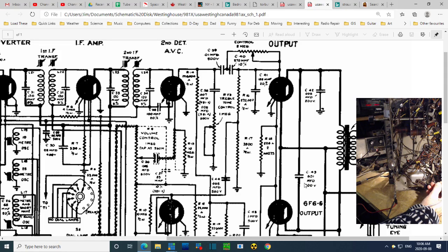That shouldn't make any real difference here unless it's huge, because you'd have to have a huge current flowing in the winding of the output transformer to cause a significant voltage drop. So this is one of the challenges with all this radio work: current measurement, current flow in plate connections, not the easiest thing to determine.